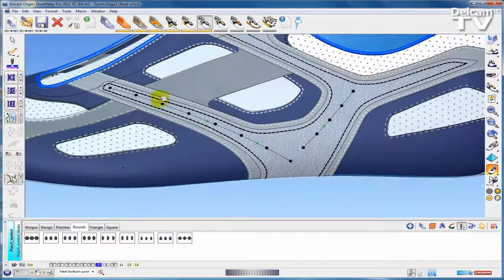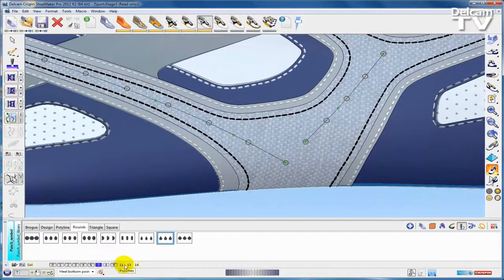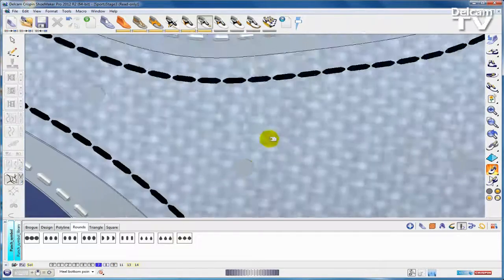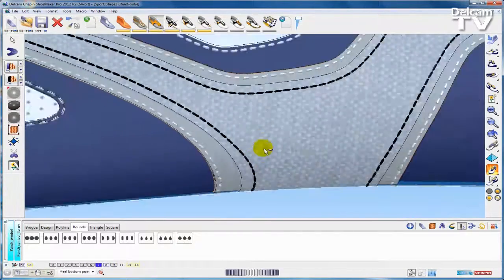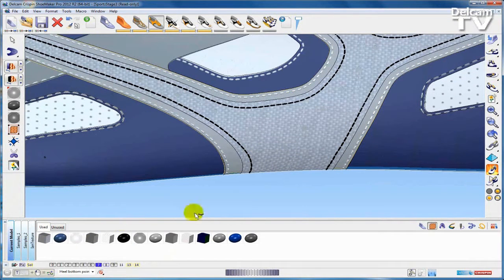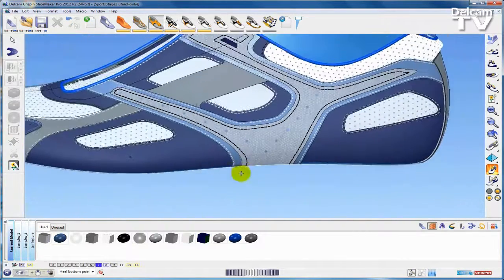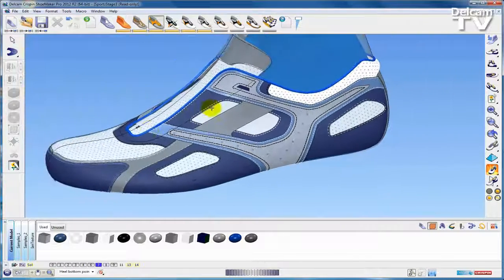And then I'll select both sets of punches together, and we can choose whether we're punching all the way through to the last or whether we're just punching through the first layer of material. So in this case, I'll say we just punch these straight through to the first layer of material, and I'm going to put the punches onto another level, and if I zoom in you can see there that we've got our holes punched through the design. Just to highlight that a bit more, I'll zoom in and drag and drop a different colour so the holes highlight much better. Okay, so those are punched holes.